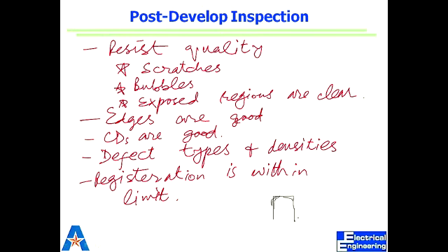So we make sure that the CDs are fine. There can be multiple shapes, multiple features, a different variety of shapes of those features at that size, which we want them to come. Maybe circles, maybe lines, maybe distance between two lines. Not the line itself, but the pitch, how often. Yeah. The node is different from the CD?